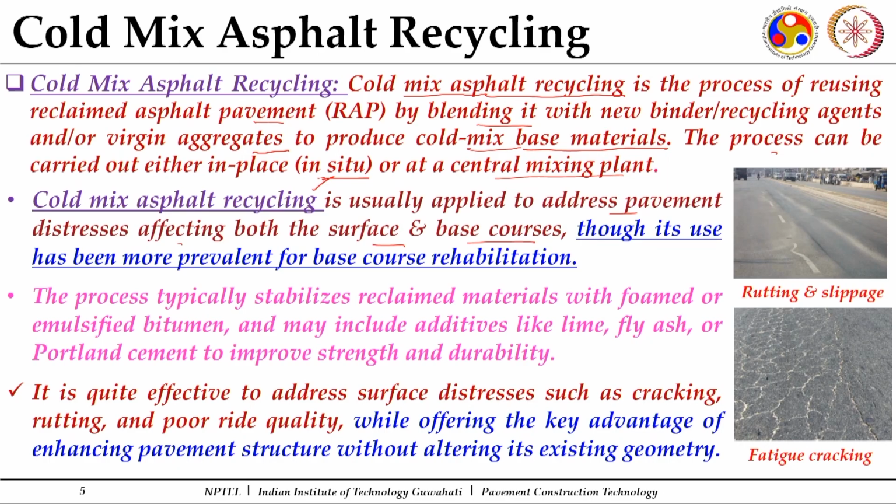Any issues related to these bound courses can be addressed, though its use has been more prevalent for base course rehabilitation, because if there is some issue with the bound bituminous courses, they can be addressed with cold mix asphalt recycling.